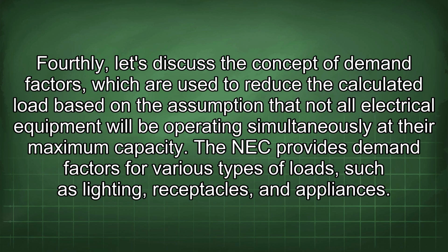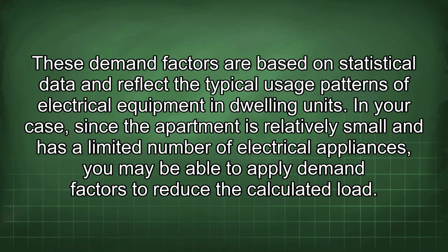Fourthly, let's discuss the concept of demand factors, which are used to reduce the calculated load based on the assumption that not all electrical equipment will be operating simultaneously at their maximum capacity. The NEC provides demand factors for various types of loads, such as lighting, receptacles, and appliances. These demand factors are based on statistical data and reflect the typical usage patterns of electrical equipment in dwelling units.